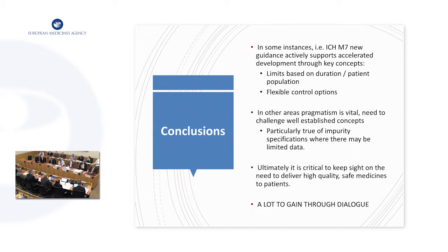Well, the bias relates primarily to solubility. We have a very conservative scale in terms of solubility. It ranges from 1 to 10. Now, we know in certain circumstances, in a recrystallization, in a purified solvent, with control over the recrystallization rate, where your impurity is structurally very different to your API, you can see significant purge way in excess of tenfold, and actually, in some cases, 1,000-fold.